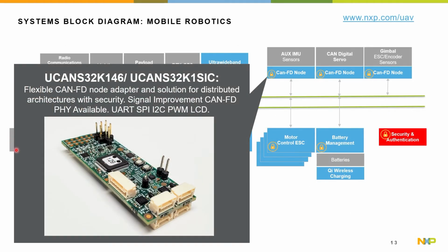And in order to support UAVCAN, and you'll see that there have been a number of our colleagues here at NXP presenting on UAVCAN and talking about this new or updated standard, UAVCAN V1. We prepared what we consider a node board, and that's literally a quick small form factor adapter. It's got an S32K1 automotive processor. It's got dual redundant CAN buses, so this allows a daisy chain in and out, and then there's CAN 1 and CAN 0.